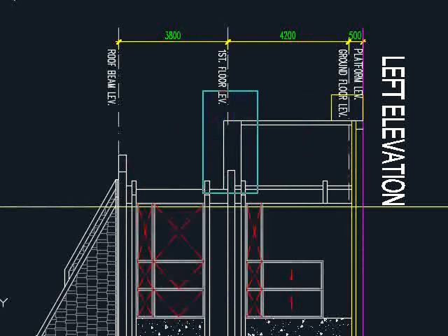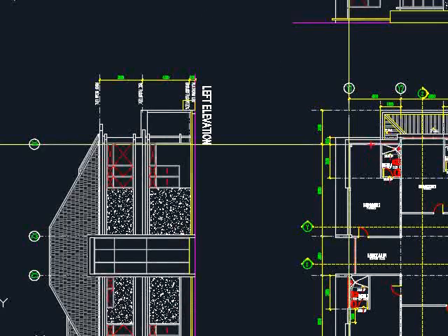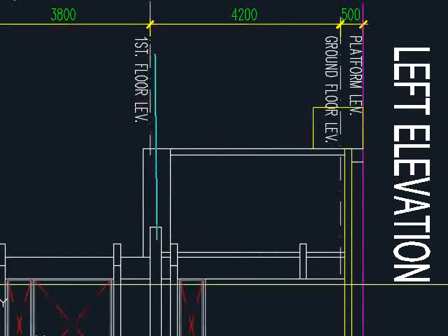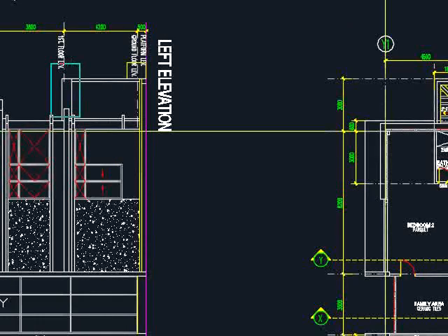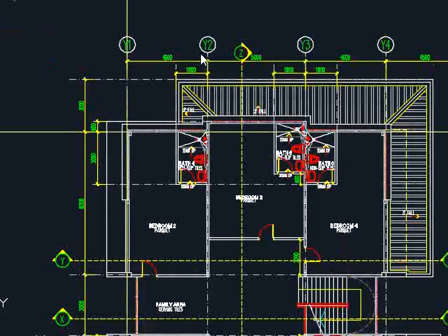Also, if you look at this, which is meant for the roof here, by looking at the level of the first floor, you know that this one is a gutter, and it is slightly higher than the first floor level. Therefore, when you construct the gutter, provide detailing, make sure you cater for this additional height as compared to the first floor level. We shall look further into this gutter here.